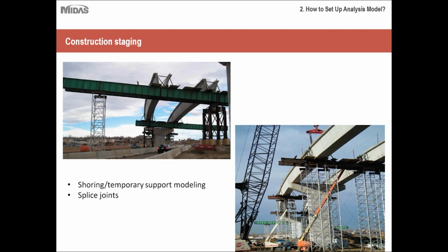Then let's move on to the fourth challenge, which is the construction staging itself. As you can see, all these bridges are heavily supported on their shoring, and depending upon the road alignment underneath it, you can either have just nice support right under the bridge, or you can go for bent caps and then provide shoring.